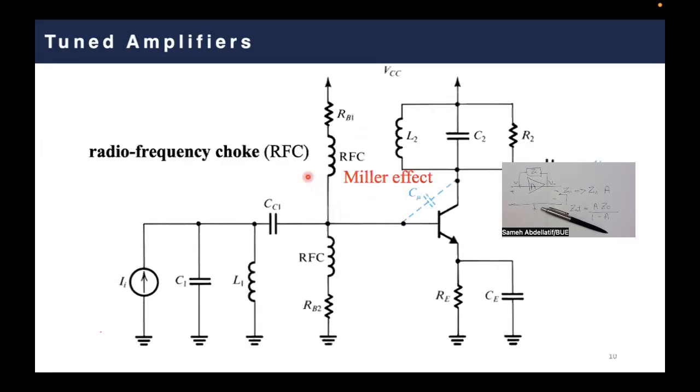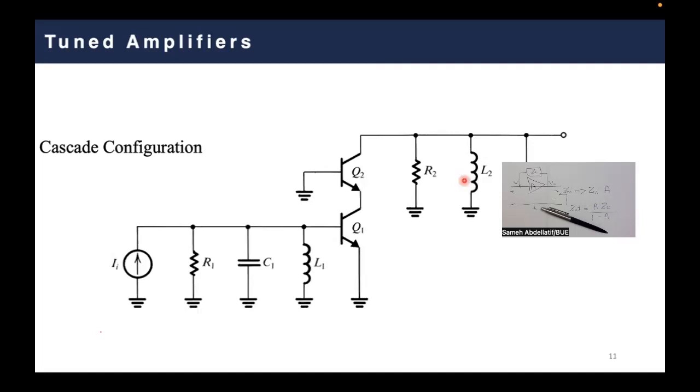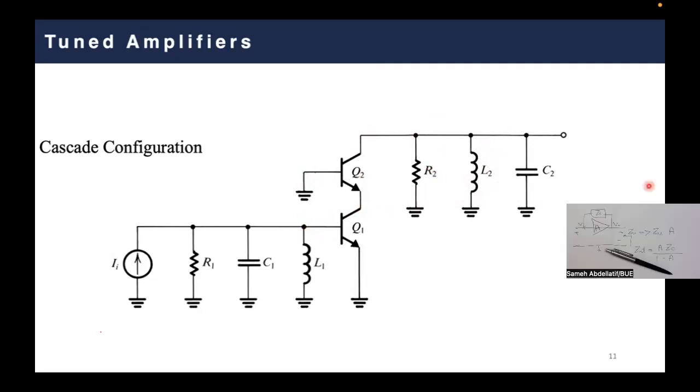Again, if you remember, a feedback capacitance is the capacitance connecting the output to the input. Here we don't have this capacitance because simply you are connecting the input to an intermediate point in the circuit, which is not the output. And here you are connecting the output to the ground, which is a capacitance that can be added here. And you can design your C L in order to compensate the effect of this capacitance during your design.